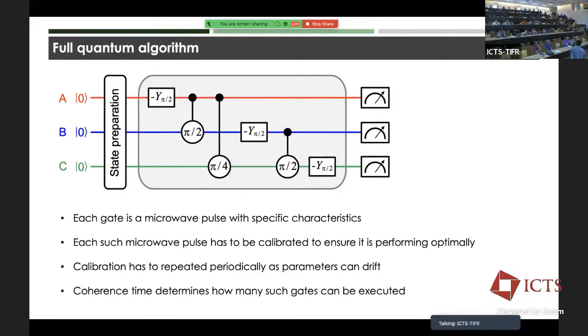Absolutely. People have done these experiments. I've also done some experiments earlier where we put in a noise bath and then see how that affects it. You can do all of those things. So these noise baths can be introduced again using some arbitrary waveform generator to create the noise spectrum. They can come from your measurement lines, the drive lines. They can also come from the flux lines.